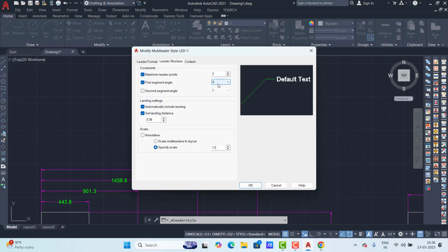So this will have a multi-leader. Now here in the panel, I have Add Leader. If you want to add a leader, just click Add Leader, select this leader, and whichever location you want to present, it can be presented this way. But this one is also incomplete in 4 steps. So it is better that you make a minimum of 3 steps and press Enter. Similarly, to remove a leader, just select and press Enter. So that is remove and add leader.